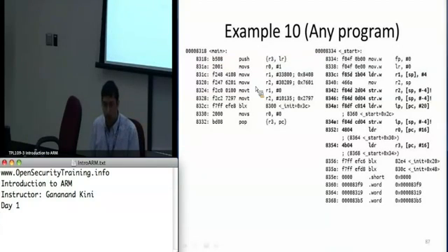So here I just put, you can take any program. This is just a main program from a lot of the examples. You'll see pretty similar stuff where they're taking variables and putting them on the stack. But since I was using pointers in this example, it'll store that value at that address based on the stack pointer here. So the address is on the stack, and it's using that address to calculate an offset. It's like an array, basically.